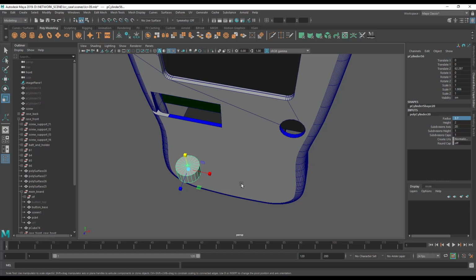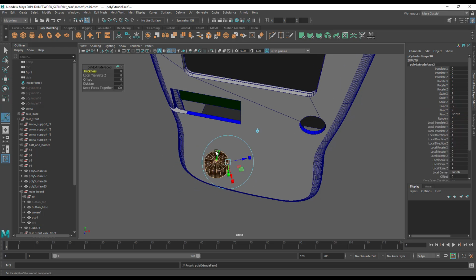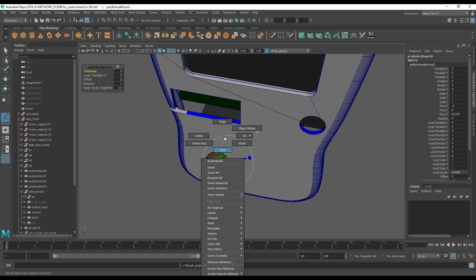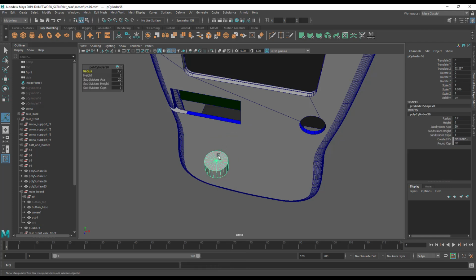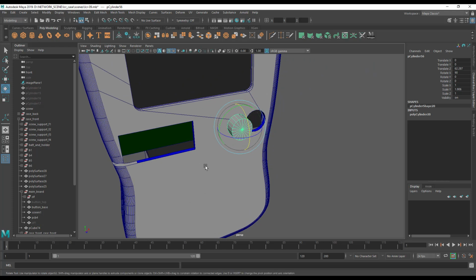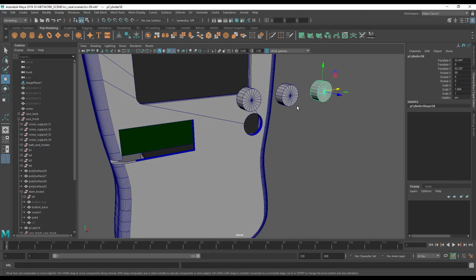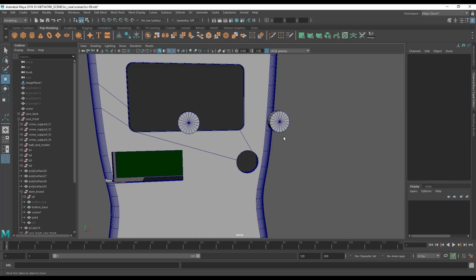Now in this case this is going to be a little more tricky because, let's see, so let's E to rotate. Oh, actually no, I hit extrude, so make sure I undo that extrusion. E to rotate, just get them down to 90 degrees, there we go. And I need a few more of these, but I need them a certain distance apart. I don't just want to go, you know, D, W, one there and kind of one there and just call it close enough, because it's not.